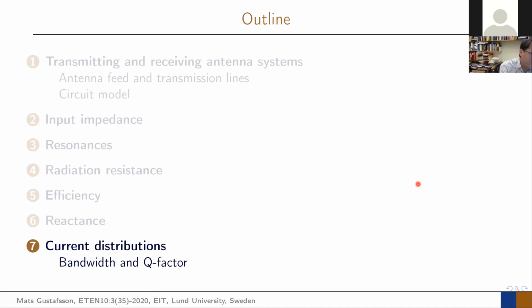So those are some interpretations of these antennas. In some ways, it's hard to get the reactance, but you need to know it because you need to determine the resonance frequency for antennas, one of the most important parameters. And you need to, in some way, search for that one when you design your antenna. Like your patch antenna, you should try to make it resonant at the Bluetooth frequency. That means you have to have the right length of it.